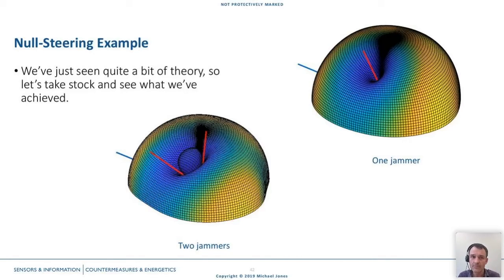And so it's filtered it out based on the direction of arrival. And the diagram at the bottom there is showing the same thing, but with two jammers. So we've got two red lines showing direction of arrival of two different jammers. And you can see it sort of punches a hole in the antenna pattern around both of those. So it's quite possible that occasionally you will lose one satellite or two if they happen to be coming from a similar direction to the jammers.